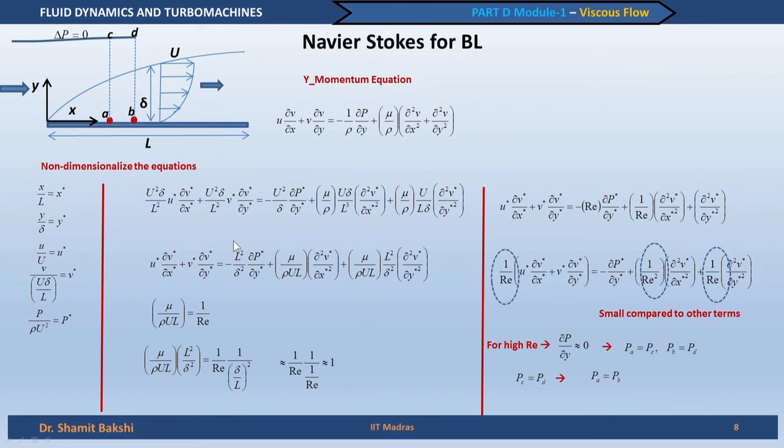So what it essentially means is within the boundary layer del P by del x is 0 for the flow over a flat plate. This is quite general, del P by del y is 0, it can be extended to flow over curved surfaces also, but we will not get into that. We see here simply that whatever we assumed in the last lecture, that the same pressure gradient outside the boundary layer is imposed inside the boundary layer, is actually correct, and it can be mathematically proved like this.